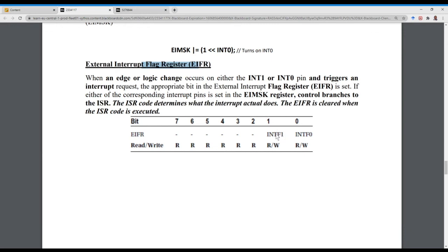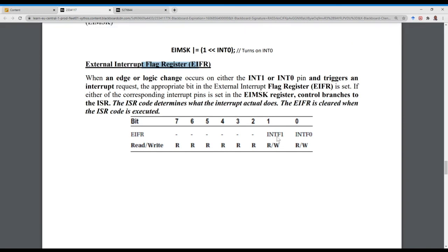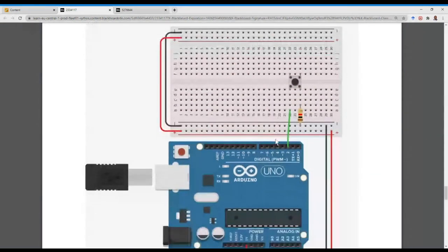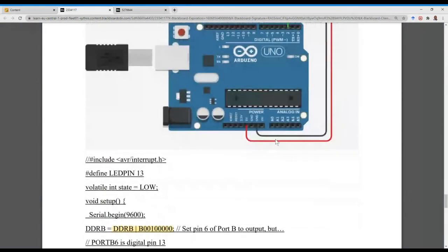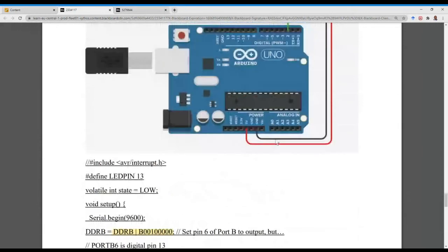As soon as there's an interrupt here and the previous conditions are already met, the processor will ask what the actual interrupt service routine is that it needs to run. So it will just jump to run the interrupt service routine. Those are the registers that we need to set, and I've got a bit of code here that I will explain to show you how interrupts work.